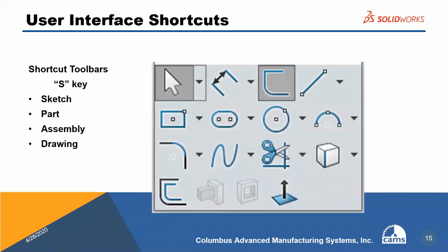And you saw me use some of this last week if you were here, because as we were talking about splines, it was no real trick to move my cursor to where I needed the spline to generate from, and then poof, this little pop-out toolbar came out. Well, the way the poof happens is, you can't see, but I'm selecting the S key on my keyboard, and that generates this Flyout toolbar.